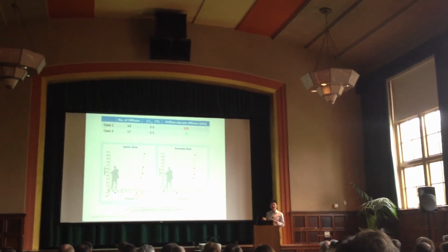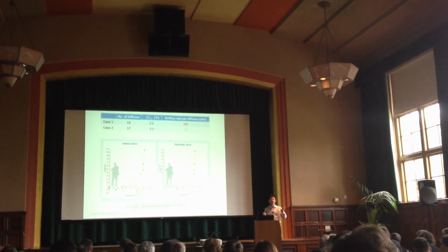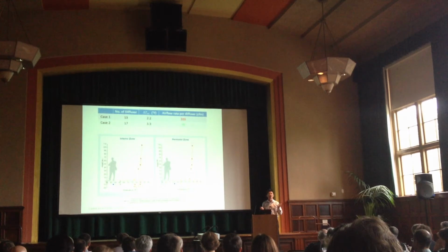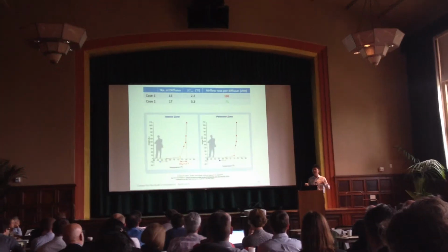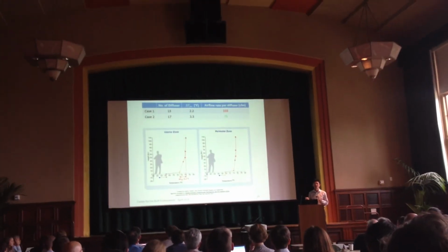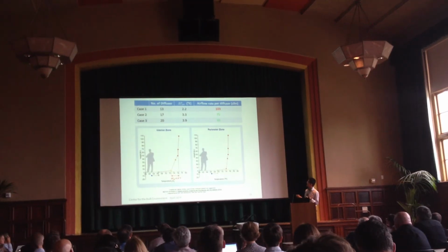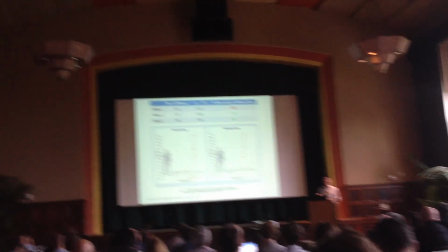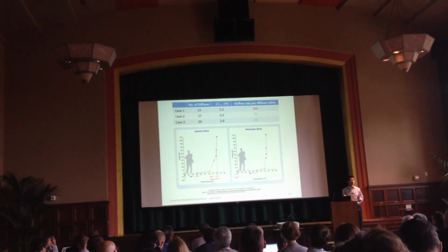Let's say the cooling load is very high some days, you increase the supply airflow rate, and suddenly the airflow rate will not exceed the limit of each diffuser. So you want to have more flexibility. We can add a little bit more diffusers. At the same time, each user can have control of their diffusers to create better thermal comfort.